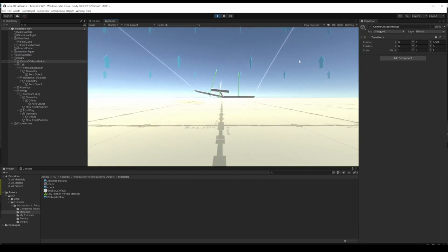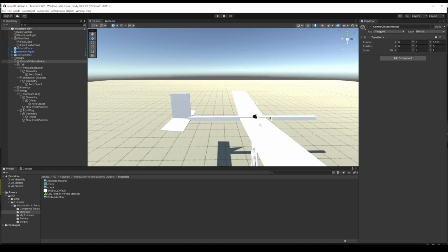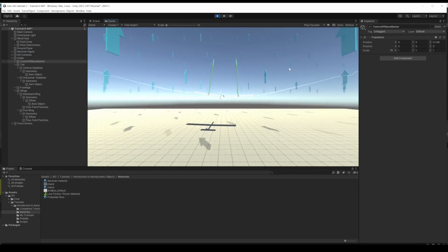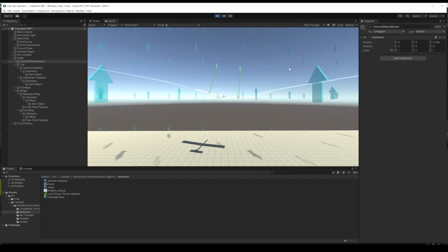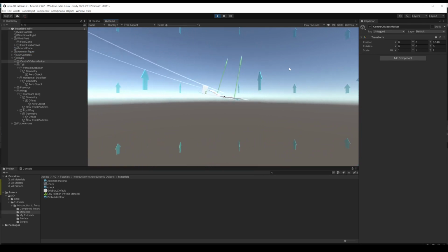In that case, it is flying, but because it's very nose heavy, it's just going to be flying in a very fast dive. Our happy spot for the centre of gravity is going to be somewhere around here, roughly back to where we started. That's slightly further back. But there we go, that's a happy plane that's stable and trims, so it's flying nicely.